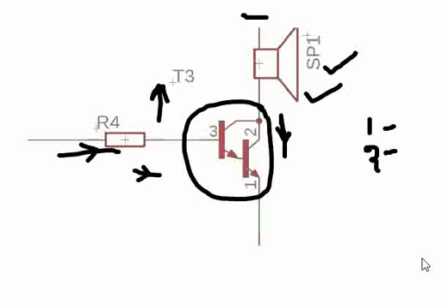So this is about the Darlington pair. Please post if you have any questions. Please post your observations on the Darlington pair and what disadvantages you have seen. Definitely there are some disadvantages. Considering the first single NPN circuit that we have seen, the turn on of the Darlington circuit takes some time longer than the other one, which is one disadvantage that we can see. Hope we gave a glimpse of the Darlington pair.